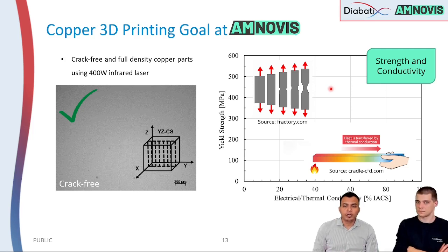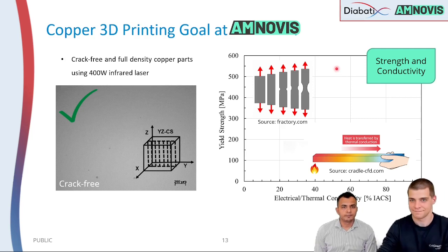And if you look at the material index for heat exchangers as per Ashby's methodology, you would see that along with thermal conductivity there is another component, yield strength, in the equation. Which means in the end you need electrical conductivity, thermal conductivity and strength. So with that I will give the floor to Niels. Thank you, Suraj.